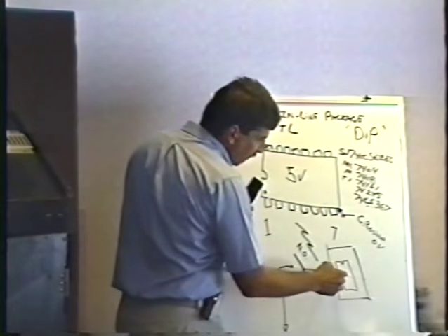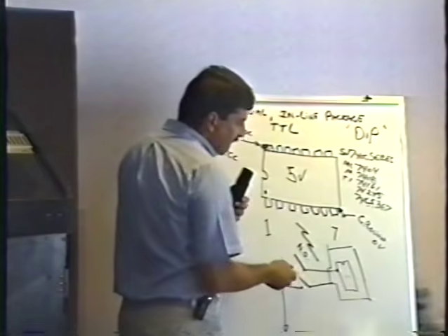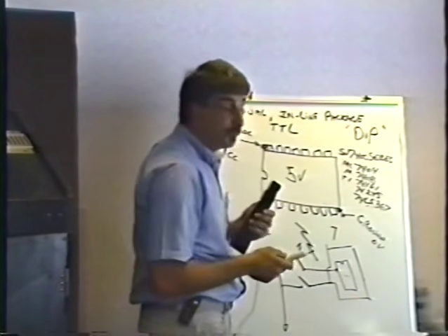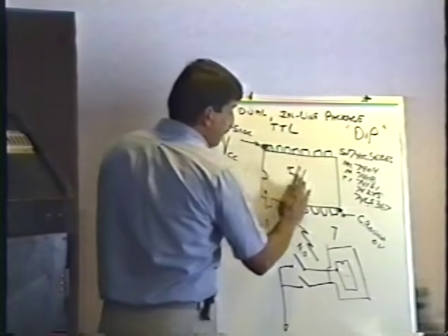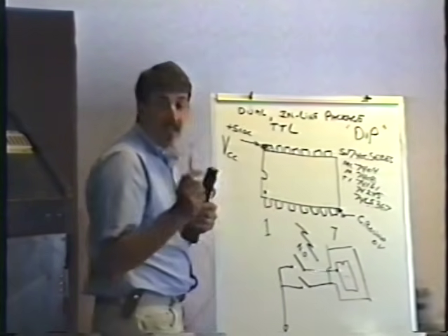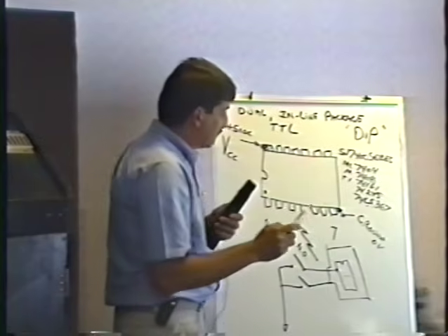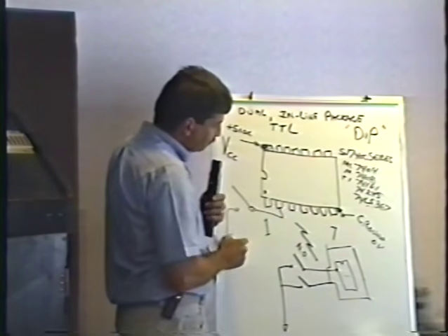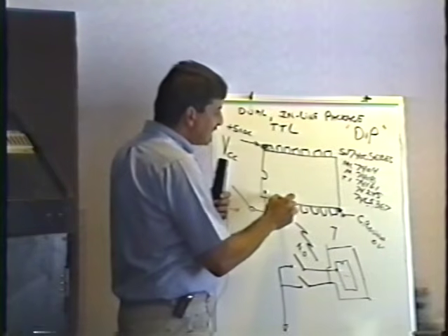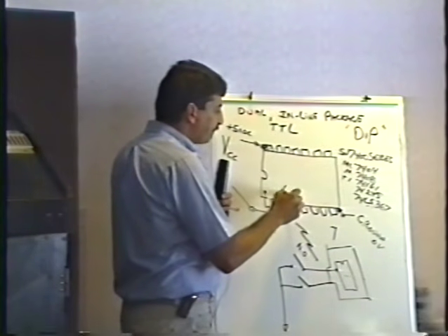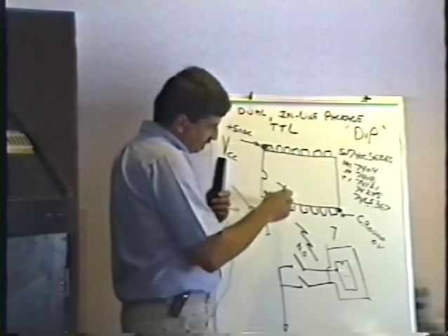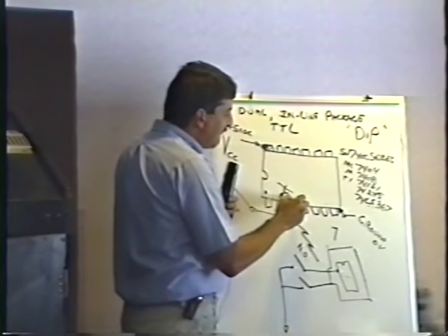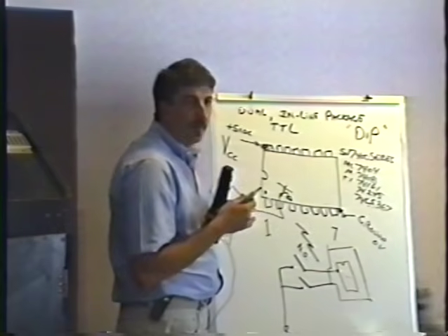Obviously, since the logic board is made of nothing but integrated circuits, that wire goes into an integrated circuit somewhere on the board, and it blows the chip. What it does, though, fortunately in a way, is that the inputs almost always short circuit. Let's say that this goes to a switch somewhere like this. Inside this thing, there's a transistor. Inside this chip, there's a mess of transistors, thousands of them, really. And what happens is this input will short to ground.